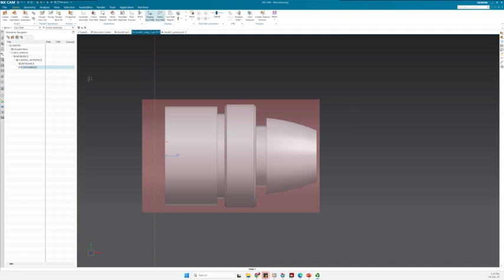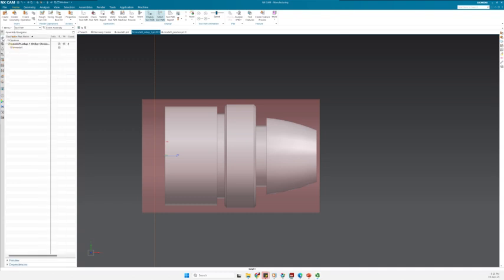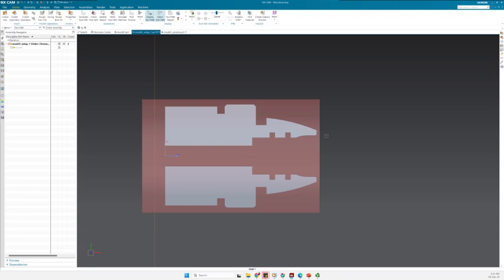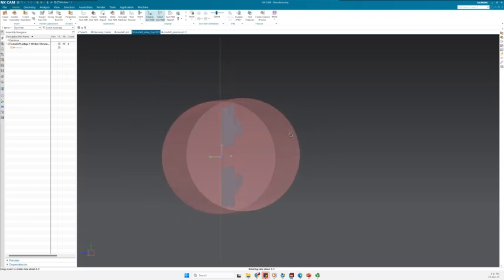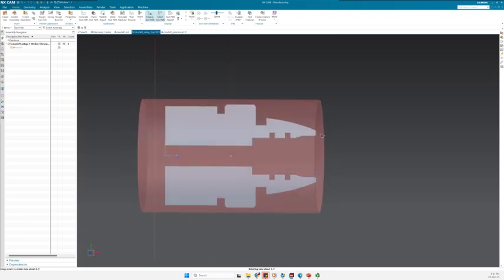Next, what we need to do is to change the way that we are viewing this part, or the rendering style. For that, you need to first go inside the navigation pane, or here. So you go to the assembly, yes, here, assembly navigator. Then you gray out the model. Then you actually have the 2D version of your part itself.